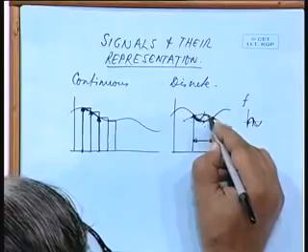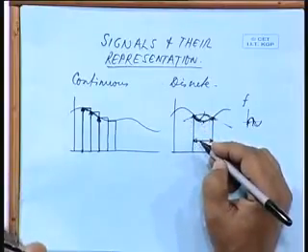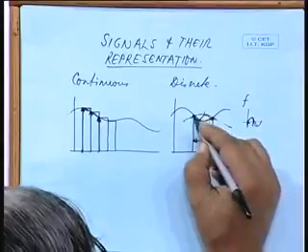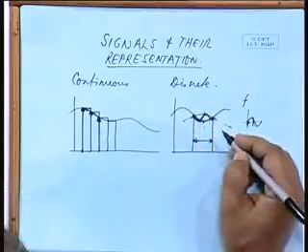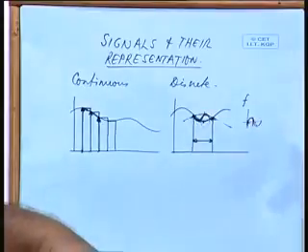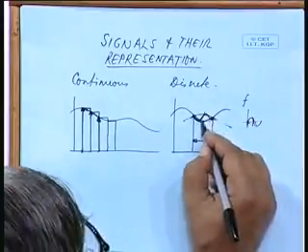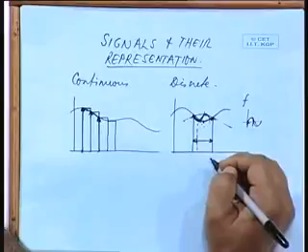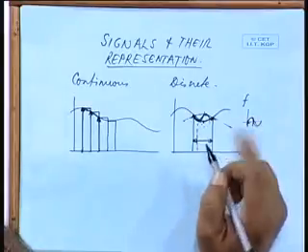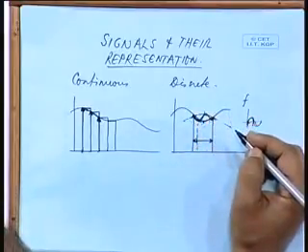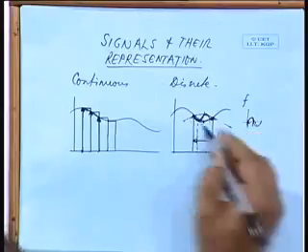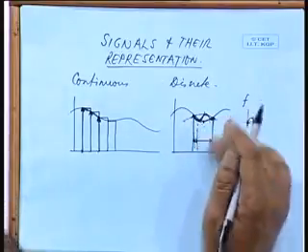There can be some more changes. There can be a peak and trough both, then that means it is varying at a much higher frequency. So, I must reduce the sampling time further to trap that change, otherwise the sampled value will not be representing the original signal.